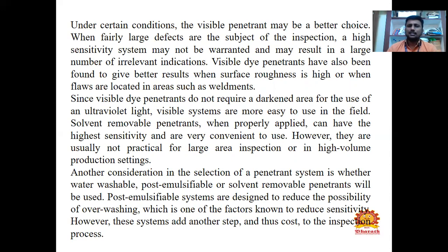Under constant conditions, the visible penetrant may be a better choice. When fairly large defects are the object of the inspection, a high sensitivity system may not be warranted and may result in a large number of irrelevant indications. The visible dye penetrants have also been found to give better results when surface roughness is high or when flaws are located in areas such as weldments.